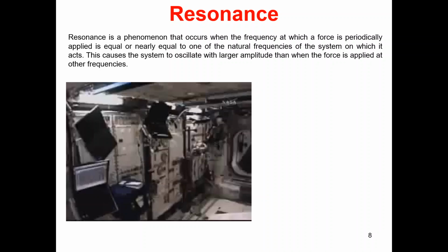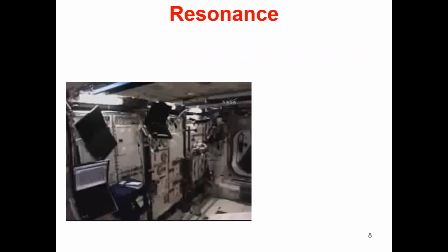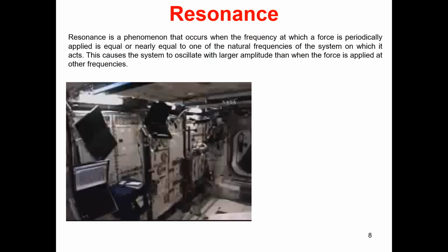One other very famous resonance case, let's define resonance again, and then we'll talk about this next case. Resonance is a phenomenon that occurs when the frequency at which a force is periodically applied is equal or nearly equal to one of the natural frequencies of the system on which it acts. This causes the system to oscillate with larger amplitude than when the force is applied at other frequencies.